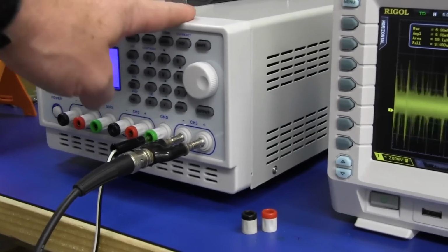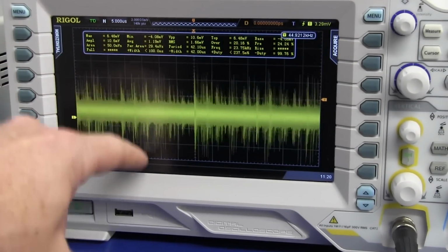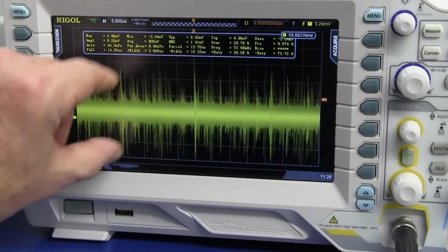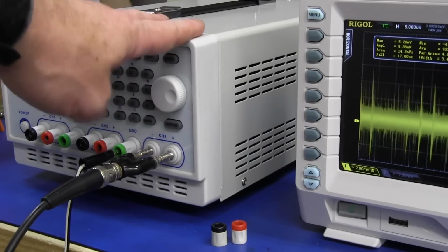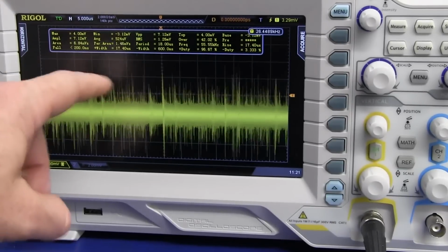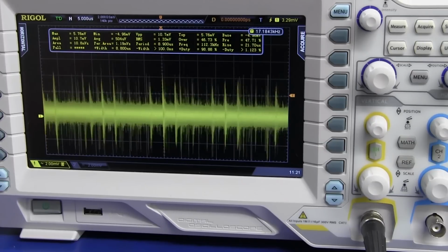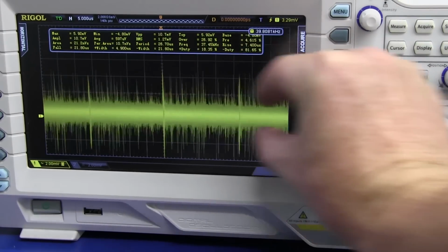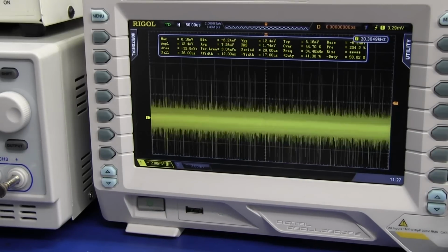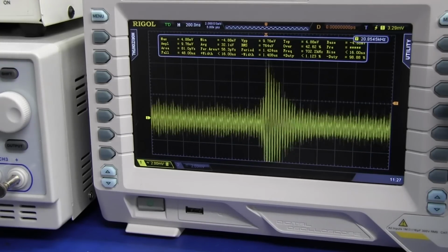So what are we going to do when measuring our A10 power supply here? We know it's a linear supply. It's not spewing out any switching stuff. So all these high frequency peaks in here are common mode noise coming from somewhere else in our measurement system. So when we're measuring the noise on a linear power supply like this A10 power supply, we know that these high frequency switching components in here are effectively common mode noise being picked up somewhere else in the system. So really you want to chop those out and only look at that in there. So as you can see, even though we got rid of that main source, we're still picking up a lot of common mode noise in here, and unfortunately that's going to be hard to get rid of.